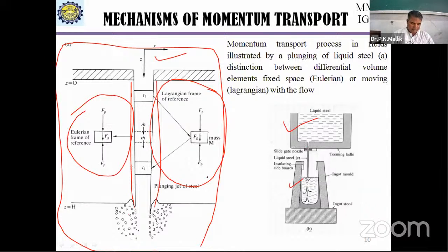For example, in the Lagrangian approach, the physical variables are described for a particular element of fluid as it traverses the flow. So as the flow is going on, you should sit on the flow and follow along the flow of the fluid. This is the familiar approach for particle and rigid body dynamics.